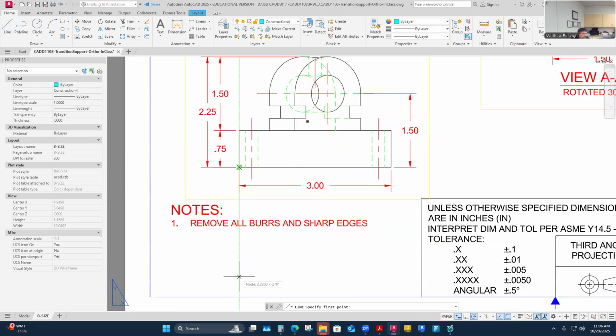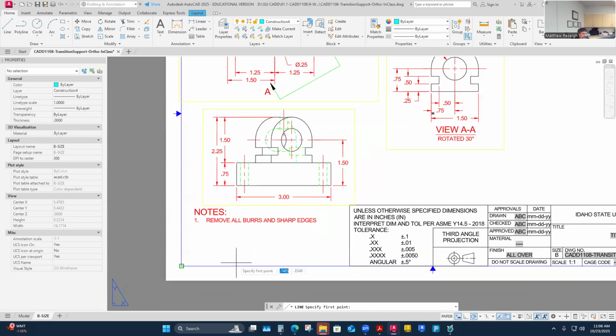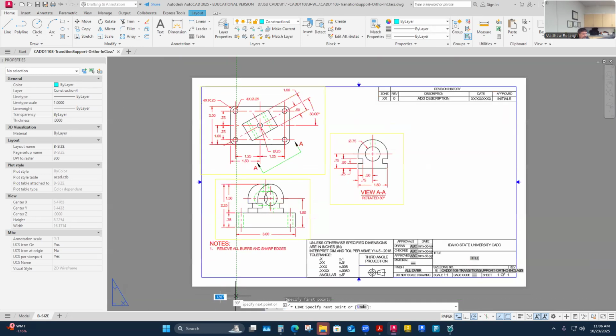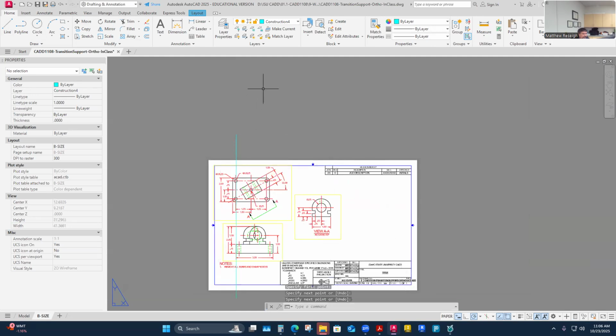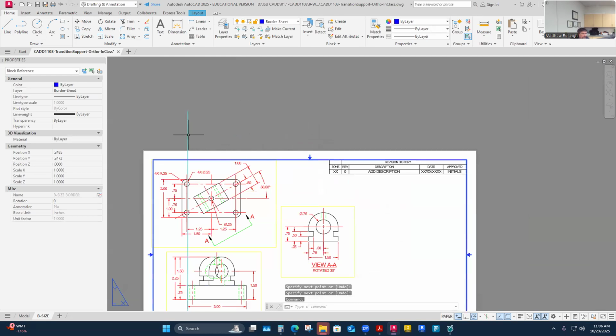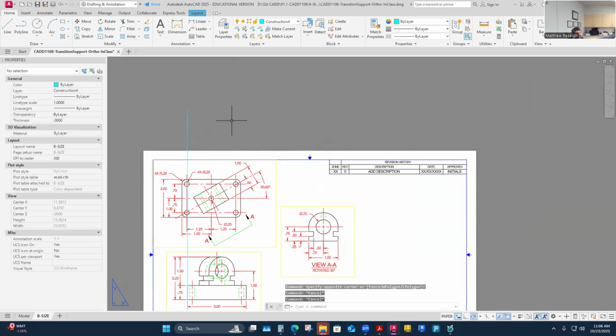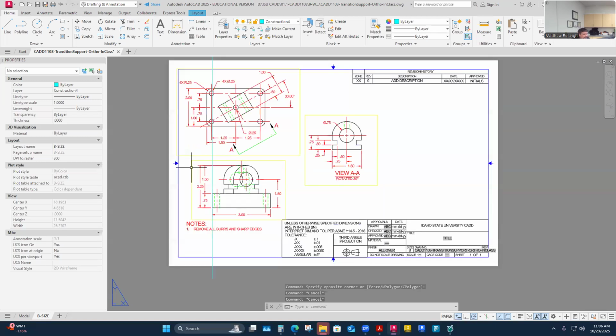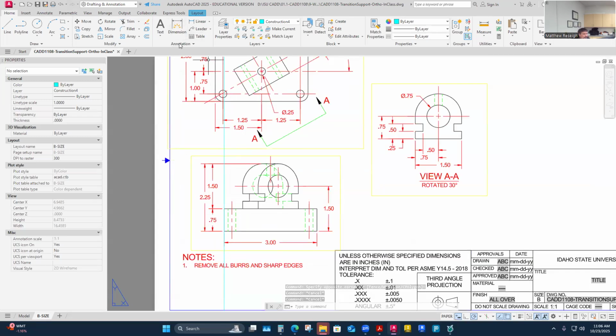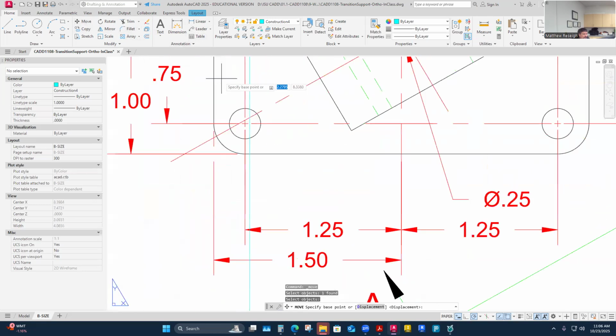Essentially, that's kind of a point that I'm gonna use to align. But I make these kind of way obtuse here just so they're clearly not part of, and that's drawn on the drawing sheet, right? That's where our borders and stuff live, where I've drawn that line. It's not in a viewport at all. It's just on top of the paper. And then I can align this top view to it. So let's do that. Move this view by this particular edge over to that.